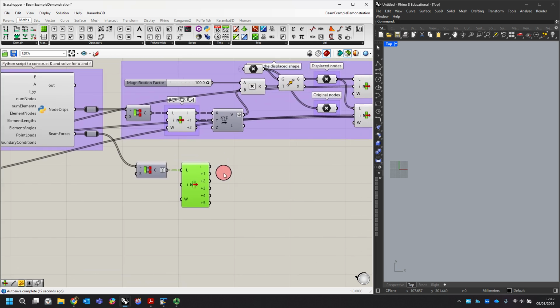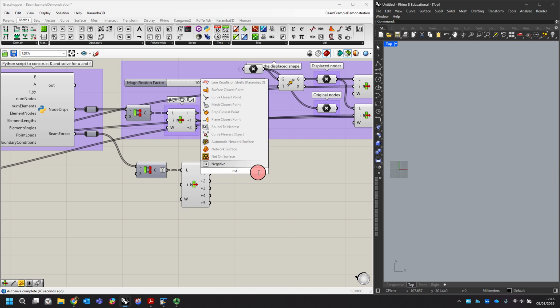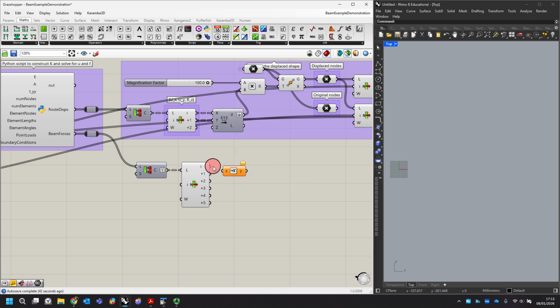And at this stage, what I want to do with those outputs is go from the local element axis to the cross-section axes. So I would look up the table that I went through in the lecture and is in the notes. But basically, for some of these, we just want the negative, and for some, we just want the actual value.